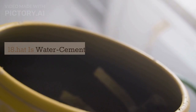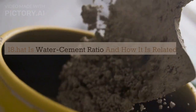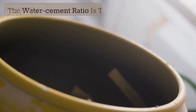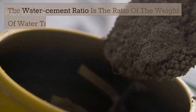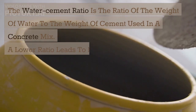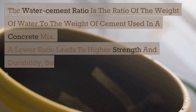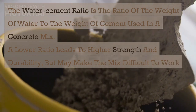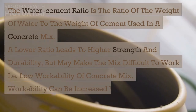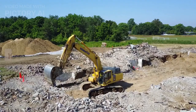18. What is water-cement ratio and how is it related to the strength of concrete? The water-cement ratio is the ratio of the weight of water to the weight of cement used in a concrete mix. A lower ratio leads to higher strength and durability, but may make the mix difficult to work, i.e. low workability of concrete mix. Workability can be increased with the use of admixtures.